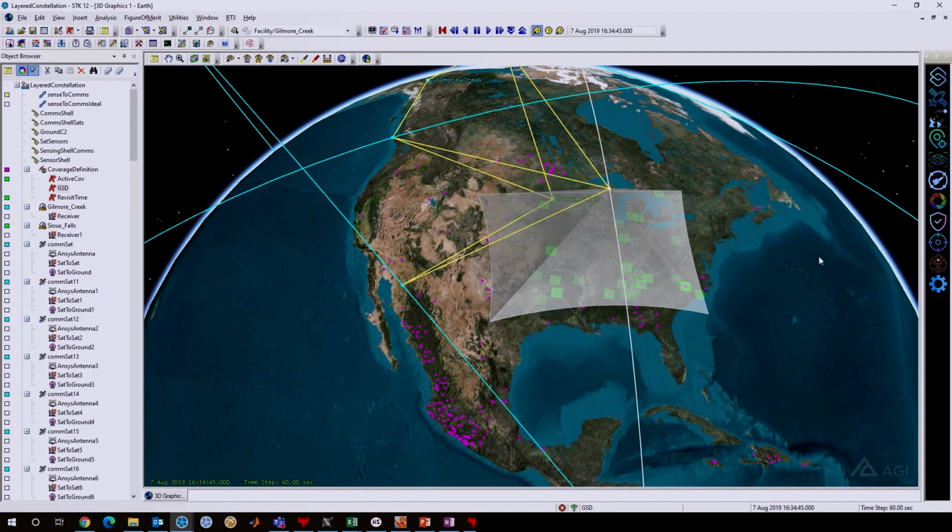And now we can take everything that we've seen so far and combine it all together to see how the mission actually operates. So here we can see that we have our satellite. It's pointing down at the ground, and each one of the wildfires that is being illuminated or is inside of the field of view of the satellite has a green box around it. This is just a basic figure of merit that shows that we should be able to see this fire. However, with the current sensor, we probably don't have the ground sample distance required in order to actually see these.